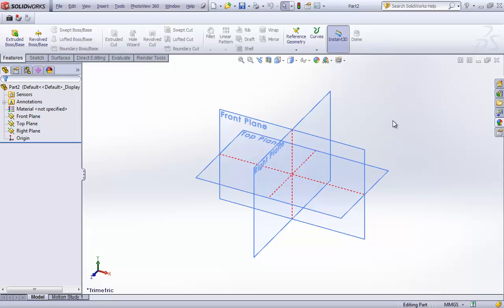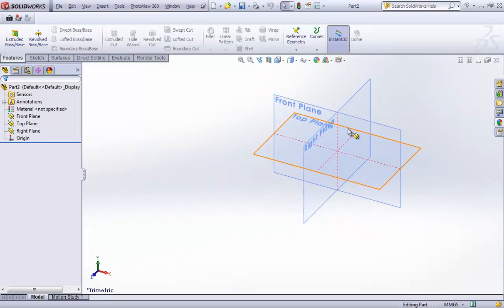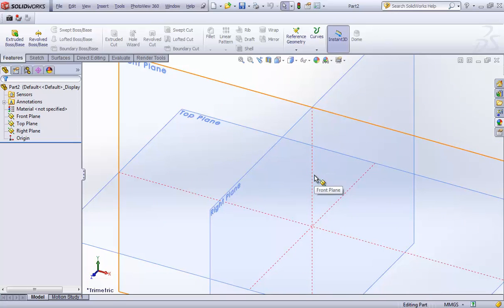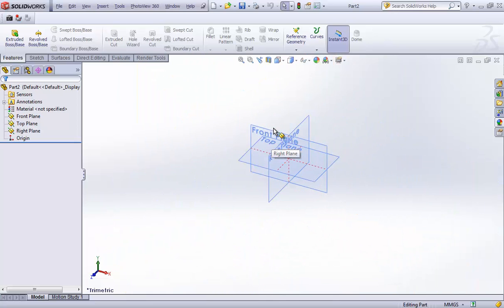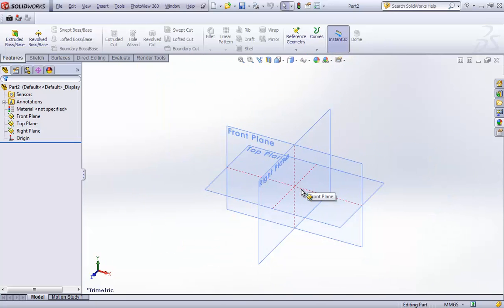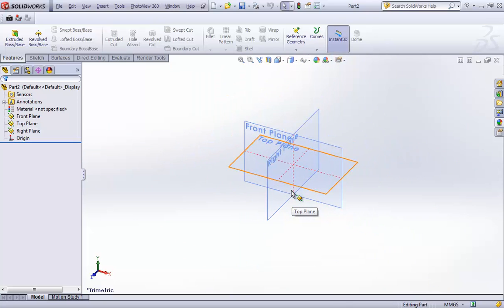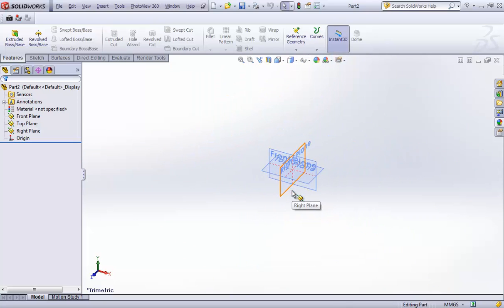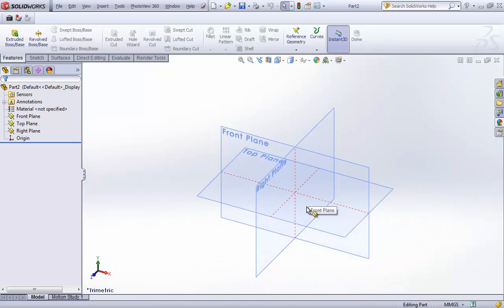You can use your middle mouse button as a zooming tool. So the scroll on the middle mouse button. If you're on a laptop, well, let me tell you, SolidWorks is no fun without a mouse. You've got to get yourself a proper 3-button mouse. So you can scroll. If you're scrolling away, in my case it's zooming out. If scrolling in, I'm pretty sure we can configure the way this works.